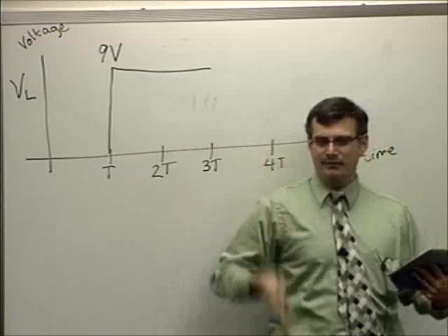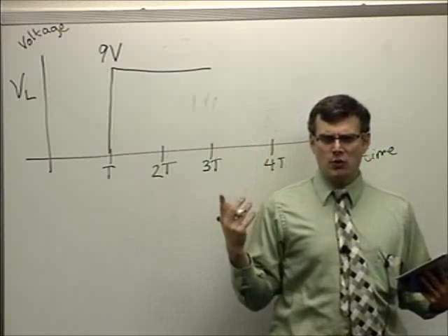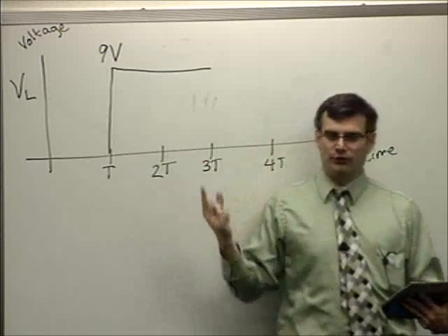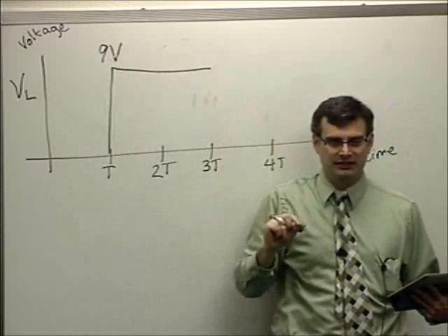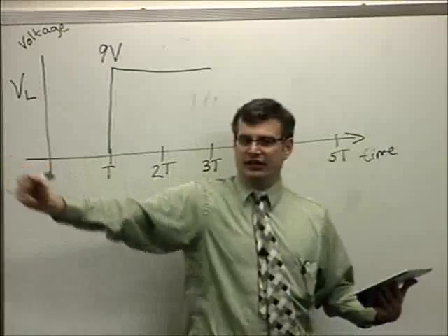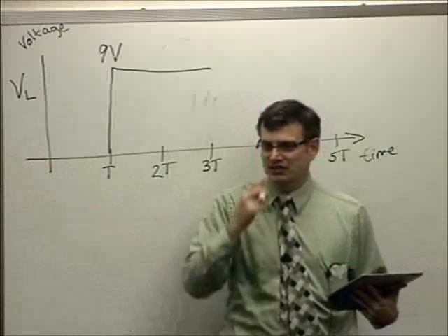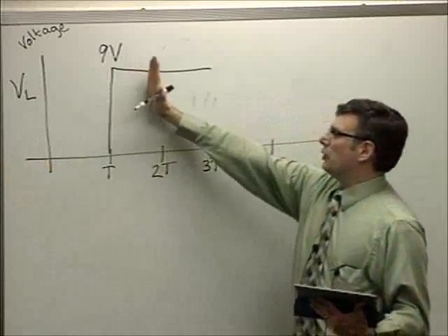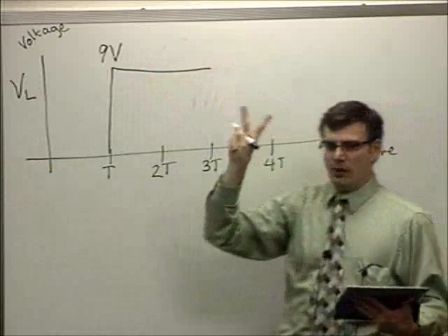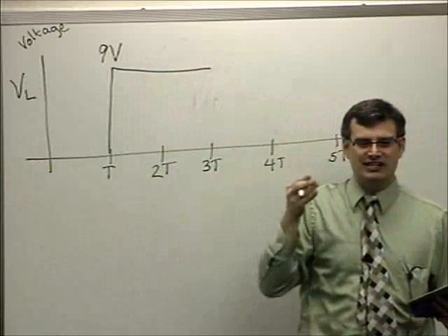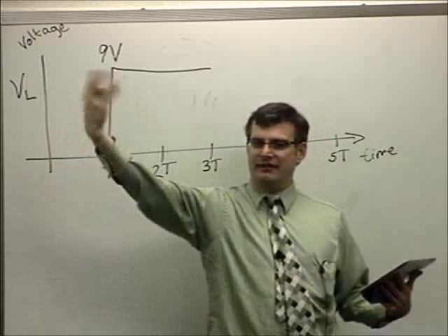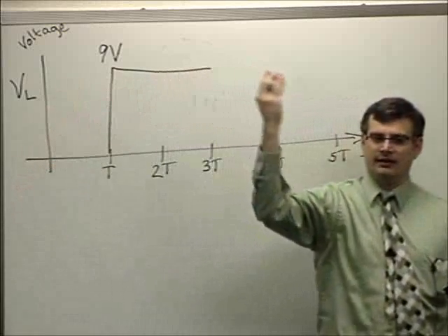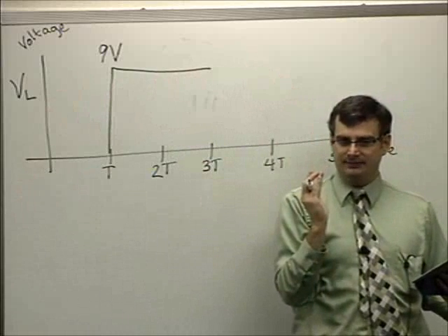It's going to hit a high impedance load, which we know will do strange things like make the total voltage jump up higher than the source voltage for a brief period of time, as it spawns a reflection that goes back to equalize the boundary conditions. 9 volts will persist for 2 transit times. We know it persists for 2 more transit times because it's going to take 1 transit time for the reflected waveform to go back to the source, and then for part of that to flip back to the load side.